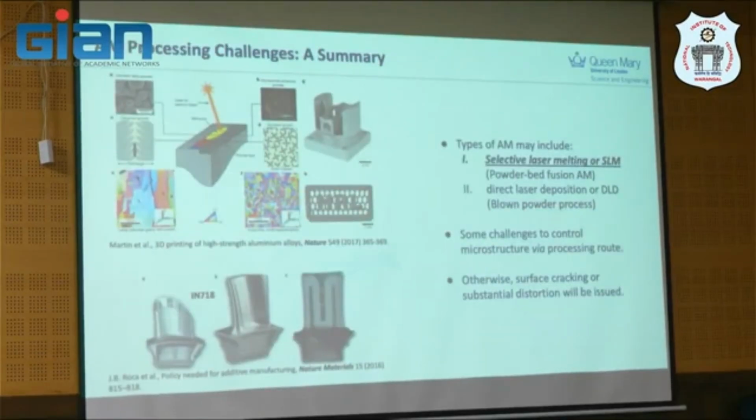Again, this is similar, but not the same. This is more detailed. This interaction actually gives rise to different solidification and hence the structure. If you know the pathway of solidification well, you may be able to change the microstructure from columnar to equiaxed, which is actually preferable in terms of strength.